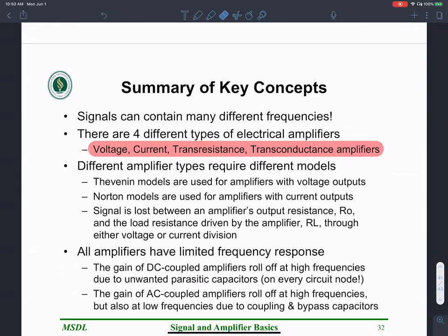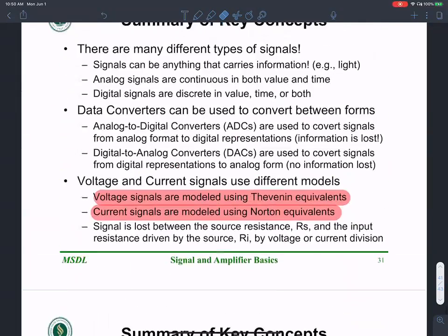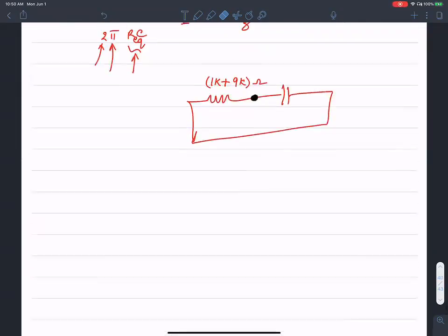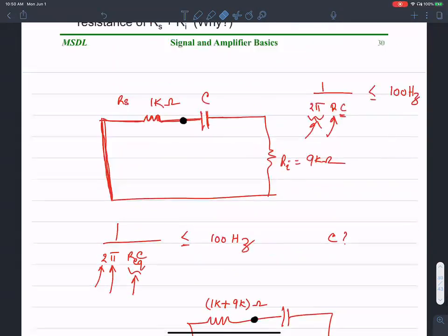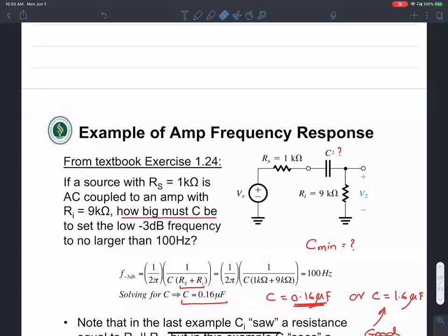Professor, is there a particular formula if we need to find the Thevenin voltage, like the open-circuit voltage? Yes, the best way to do that is to apply the test voltage, test current method to find the equivalent resistance looking into the circuit.